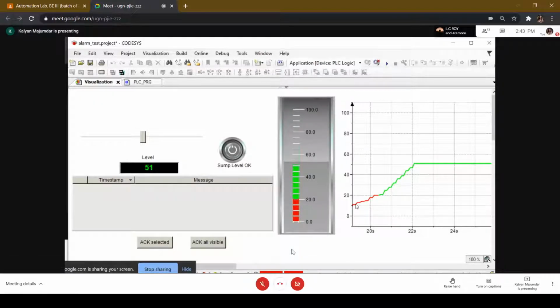for PLC programming. Alarm generation is built into this particular package. You don't need to write the software for generating alarms. You just have to configure it. For example, you've got to tell the system that you want to generate an alarm if the water level is low. Second, you want to generate an alarm if the overload condition is true. And you want to generate an alarm if the overhead tank does not fill up within this amount of time.